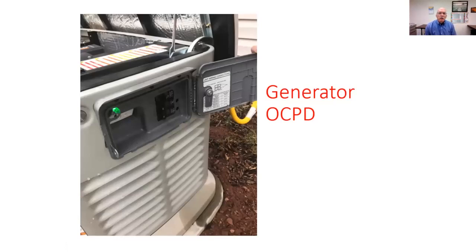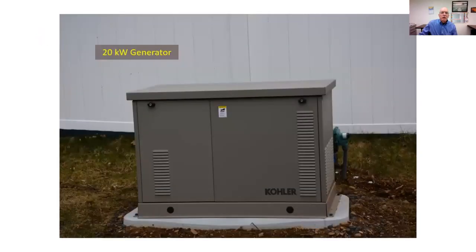Here's our generator overcurrent protective device. It's behind a locked door, and we'll talk a little bit later, but this cannot serve as that readily accessible emergency shutoff for the first responders. Now, if need be, they would get that little door open, but they shouldn't have to go through that trouble.